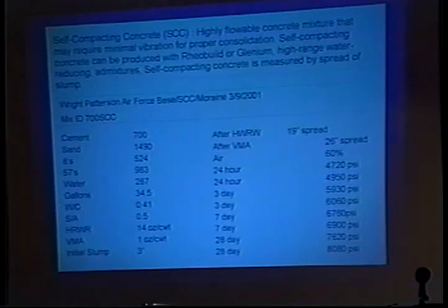And they are using a high-range water reducer, a superplasticizer otherwise known, which increases your slump so that you can work with the concrete a lot easier, but you don't really add more water. So you don't lose strength because you're adding water. Okay? And that's important.